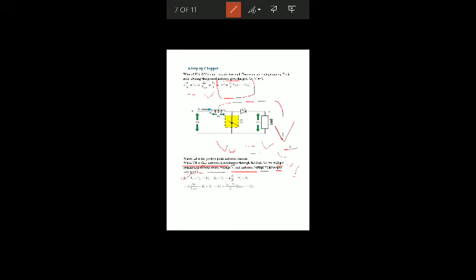V naught is equal to Vs plus VL, then VL will be V naught minus Vs. VL is equal to L di by dt is equal to V naught minus Vs. Again we represent di by delta I and dt by T off, and rearranging the terms, we can compute delta I is equal to V naught minus Vs upon L into T off.